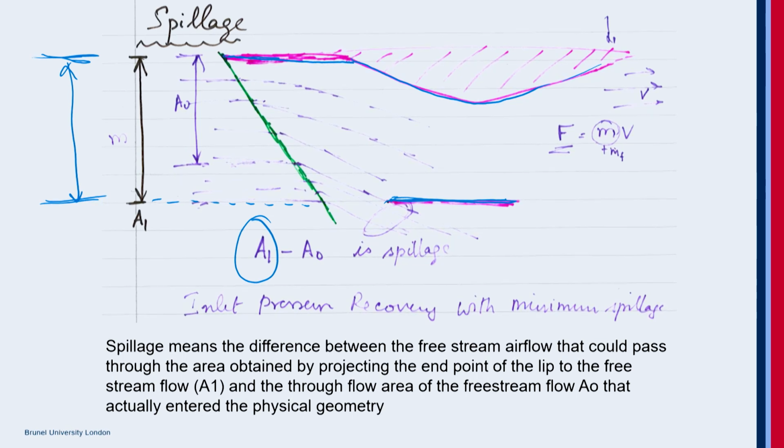But in reality, what actually happens is at higher Mach numbers, you have this green line. What you see there is the oblique shock that forms. Partially, it is required to decelerate the flow and to pressurize the air getting into the engine. Now, from the theory, what we have seen, when the flow encounters an oblique shock, the flow will turn.